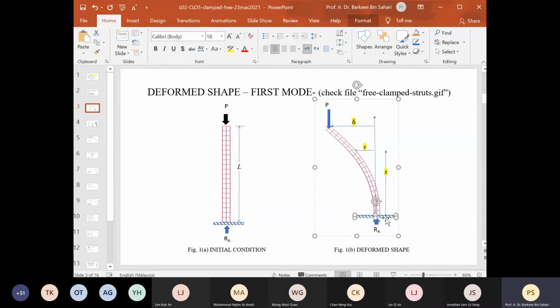And although there is no rotation, the value of bending moment is not 0. And at the top, the plane section is rotating, so there is nothing to restrict rotation, so there is no internal bending moment. So that's already explaining the boundary conditions of this particular beam. It can deflect to the left or deflect to the right.